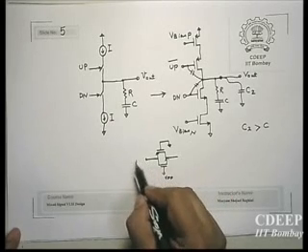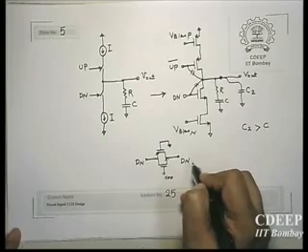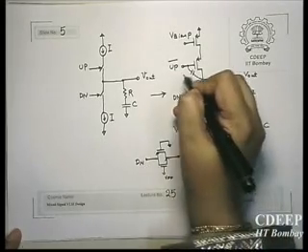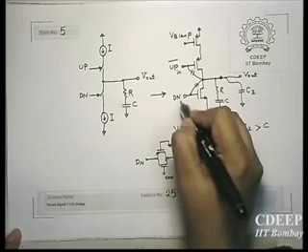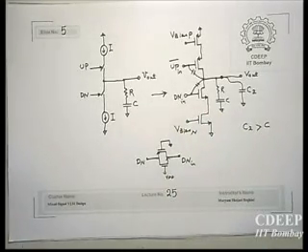But you give up to this switch and then pass it to the charge pump, so that now up and down will see the same kind of delay. There won't be any problem.